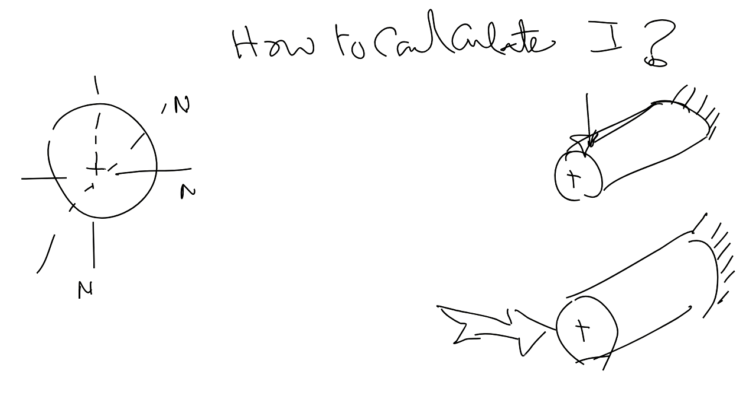But be careful about saying perpendicular to the force, because sometimes it's tricky. Because in some cases you might have more than one force. Yani, for example, if I give you F1 here and I give you F2 there, can you tell me what is your neutral axis? You will never ever be able to tell me what is the neutral axis until you do what? The calculation. What do you mean by calculation? All our business in this school is calculations, man. I mean, we'll have to calculate for both cases separately, right? Like in one case, the neutral axis will be horizontal and the other vertical. No, Muhammad, no. After finding the resultant force, there is one neutral axis here in this case.